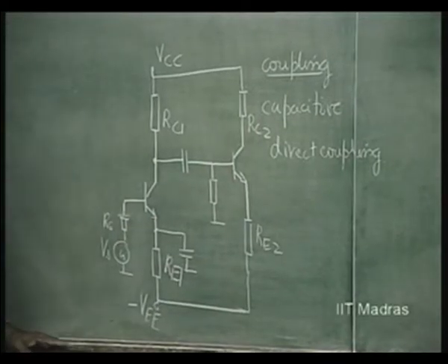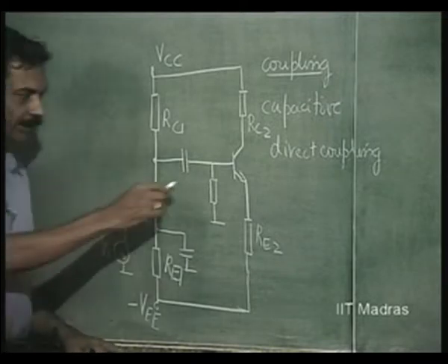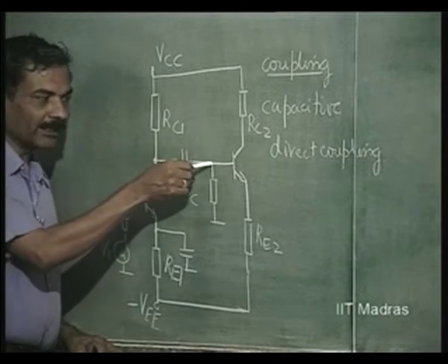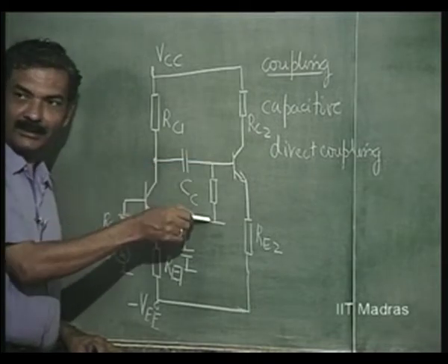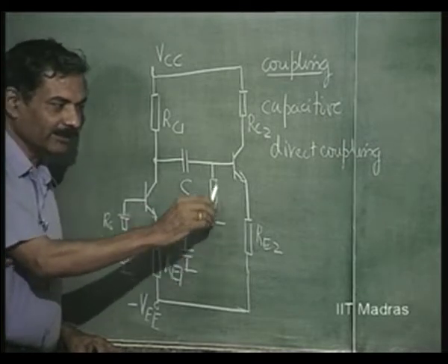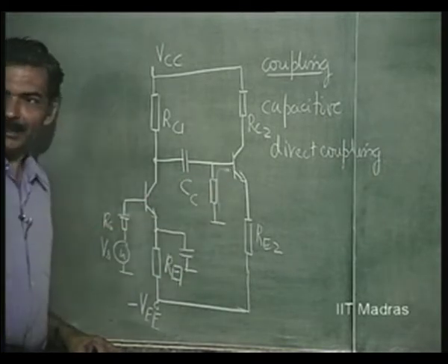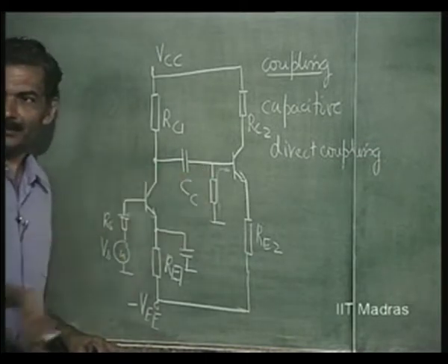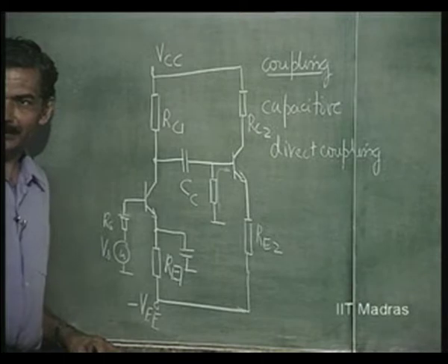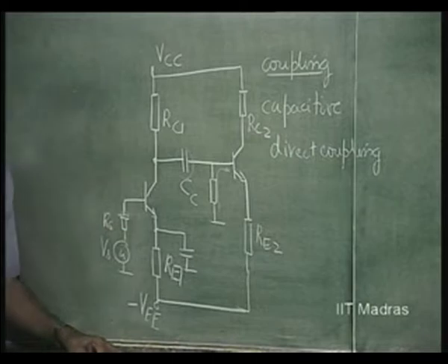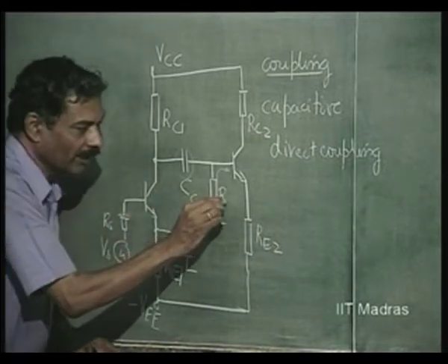So this is how I can couple. Is this clear? This capacitor CC can couple this output directly to the base. Why is this resistance needed? This resistance is needed because there is a DC base current which has to pass through. So, this resistance is a must, we cannot avoid this resistance, right? And the AC coupling is done by the capacitor. So, this we will call RB.